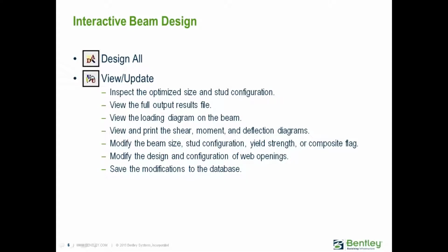After you specify all of your criteria in the RAM Steel Beam Design module, you are ready to design all the gravity members in the model. The RAM Steel Beam Design module performs an analysis and design on all of the gravity steel beams and joists in the model based on the user-selected design code and criteria. Steel beam sizes are selected from the Steel Beam Design table that is chosen in the RAM Manager. When you invoke the Design All command, this will be used to size all beams which have not been previously sized by the Beam Design module.